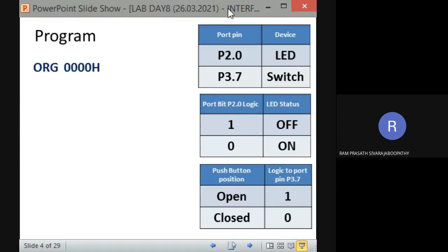This is a command we are giving to the assembler software. In the particular software we are going to use, we have an assembler. Yes, very good. It is an assembler directive. Whenever the assembler finds the word ORG, it comes to know that the lines below have to be assembled from the mentioned address. Why are we writing the program from 0000H?